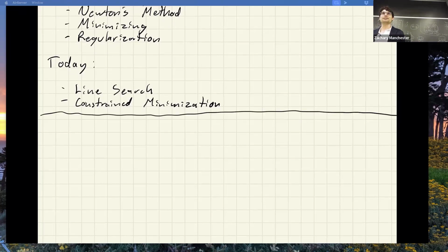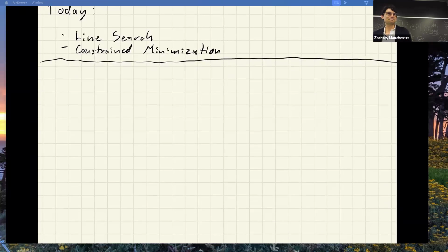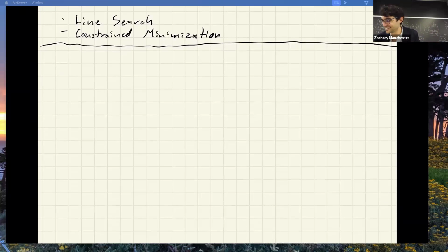Turns out Newton's method is deadbeat control. Has anyone heard of deadbeat control? Yeah. So Newton's method is doing deadbeat control on a linear approximation of the dynamics. That's what it's doing, which is cool. And I Googled this and there was nothing. So if anyone wants to write that up and have a paper, it's fun. It's where you try to zero out your error at every time step. So if I'm trying to regulate my system to the origin, I have some state error. You just try to zero out your error every time step.